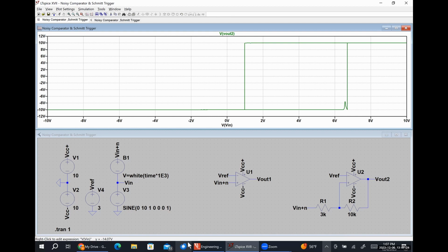The reference voltage needs to be between your upper and lower trigger limit. If it were outside of that range, you would never be able to cause the output to change state, right? So just as a heads up for your design project, if I give you what your trigger limit voltages are, you need to make sure that your reference voltage is somewhere in between, and then you'll just go through the math and figure out what resistor values you need to make things work correctly.